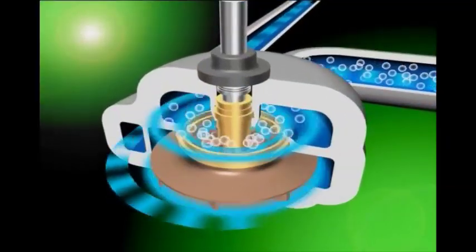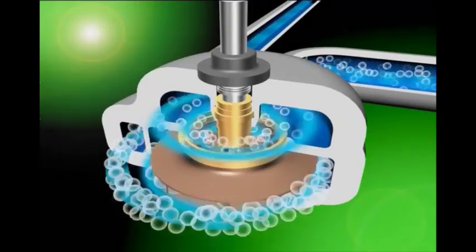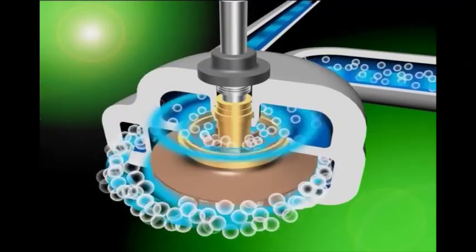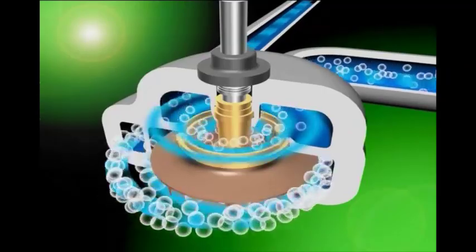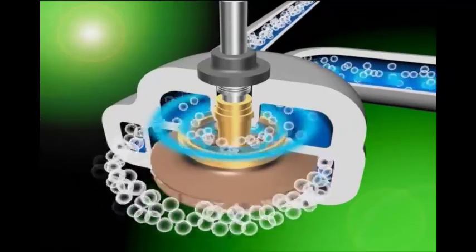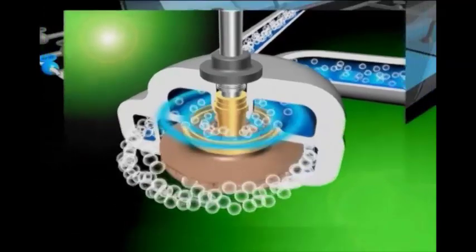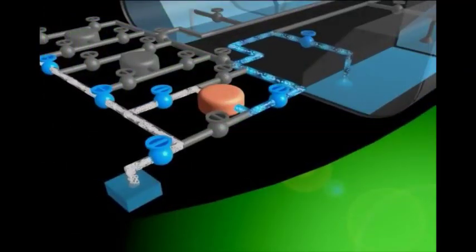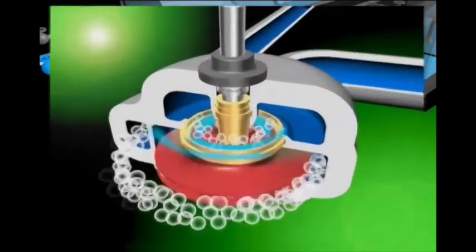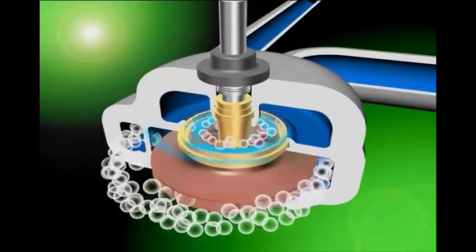Why? When a small amount of air is drawn into the pump, the air passes out of the pump together with the seawater. But if a large amount of air has entered the pump, it gathers and gradually spreads to the pump periphery, decreasing the centrifugal force the seawater receives from the impeller and disabling the pump from discharging. If the discharge amount is extremely small, there are cases where unnoticeably small amounts of air gather within the pump and build up to a level that could disable the pump. If left as it is, seawater in the pump will run out, resulting in burn.